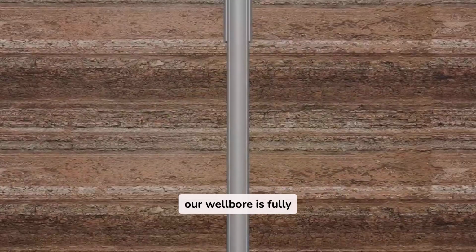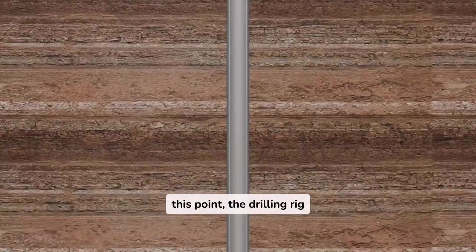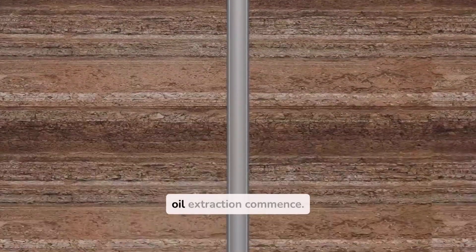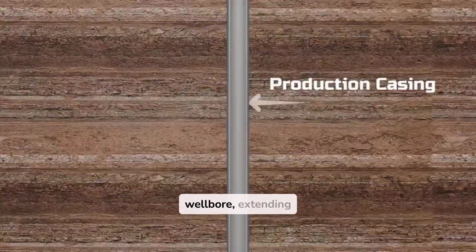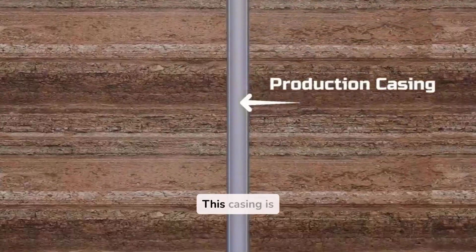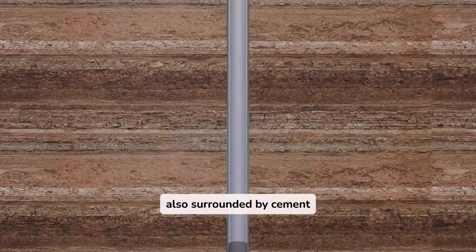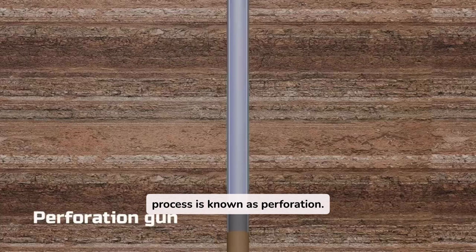Now that our wellbore is fully prepared, we're ready to begin extracting oil. At this point, the drilling rig is removed and preparations for oil extraction commence. A production casing is inserted into the wellbore, extending all the way down to reach the oil reserves. This casing is also surrounded by cement to provide additional protection and structural integrity. To allow oil to flow into the wellbore, controlled perforations are made through the production casing and the cement layer. This process is known as perforation.